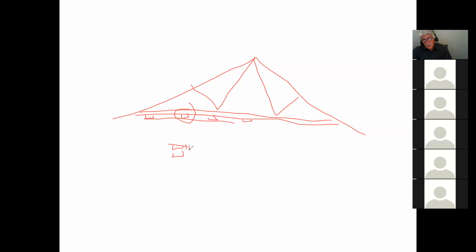You understand? There's going to be a couple of lights in my ceiling. Am I worried? You know what I mean? So you follow what I'm saying? I want you guys to be practical. I don't want you to worry about becoming academics. If these things are really a concern, we'll go find the weight of it, see how much it weighs, and add it in. Or you can say 0.2 kPa for furring strips and gutters, and make an allowance. You follow what I'm saying?